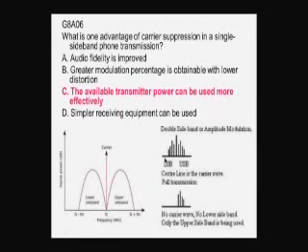And we took off the sideband we didn't want because it had redundant information. You remember that the lower sideband on the lower frequency side of the carrier has exactly the same information as the upper sideband, which is on the higher frequency side of the carrier. And so if we transmit only that sideband, we make much better use of the available transmitter power.